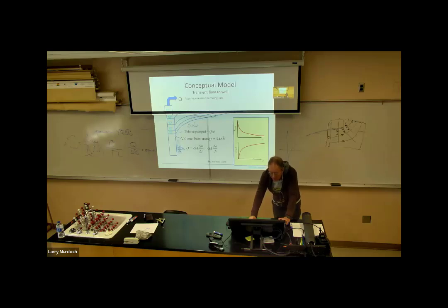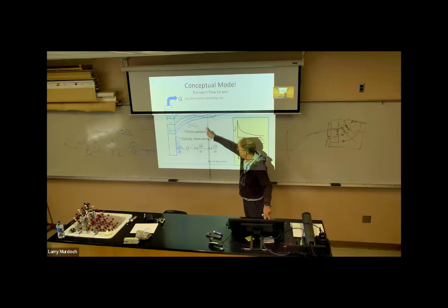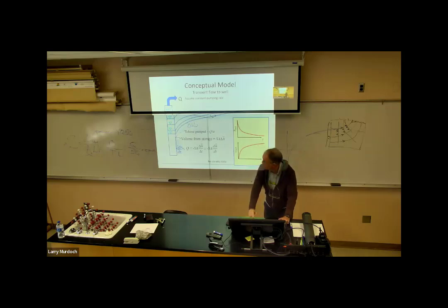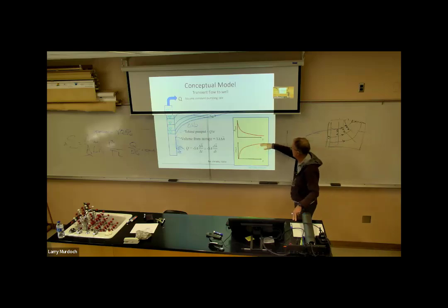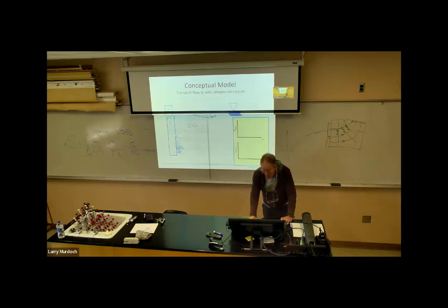One of the things that we see too is that there's no steady state. In order to get water out of the well, we have to remove it from storage, and we have to have a drawdown change with time. So this is continuously dropping, and this is continuously rising. Now, we see wells that go to steady state. That happens, it's pretty common. So for shallow wells, here's an explanation for how that can happen.